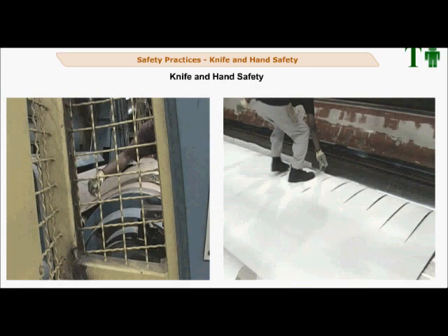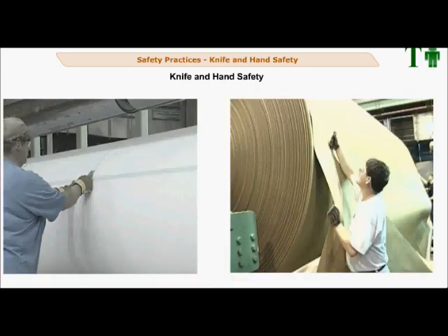Hold the knife firmly so that it doesn't slip, and never cut towards any part of your body. Do not work with two tools at once. Many Weyerhaeuser injuries have occurred when working with an unsheathed utility knife in one hand and another tool in the other hand. Additional safety training for using utility knives can be found in the Weyerhaeuser Stanley Knife Training Program.